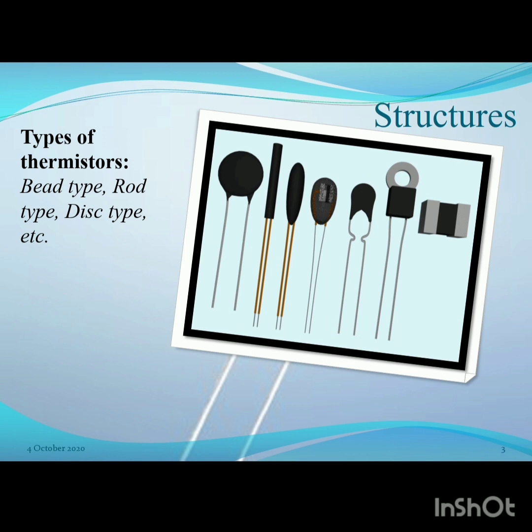That is, the thermistor is different because it is made up of ceramic or polymer, whereas the RTDs are made from pure metal conductors. So there should be a difference. Now we can say that the RTDs are useful over large temperature ranges, while the thermistors typically achieve a greater precision within a limited temperature range, typically from minus 90 degrees Celsius to plus 130 degrees Celsius.